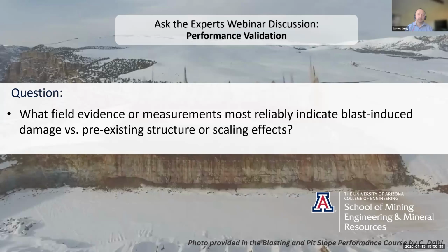Yeah, absolutely. And if you're at relatively best practice, you have a pre-designed bench plan that connects to a blasting domain that incorporates geotechnical data and geology. And so that is set, and you have a history of what you should be expecting in that blast domain.